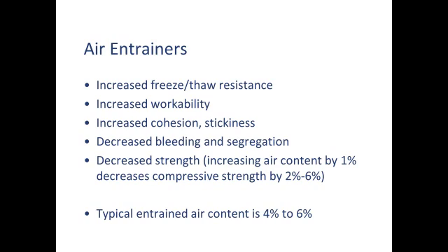The benefit of doing that is, because the air bubbles are tiny and they're sort of spherical, they do act like little foamy, spongy ball bearings. Gives the concrete workability. Also gives it some stickiness, which tends to help keep the concrete more consistent. You get less bleeding, less segregation with air entrained concrete. So for those of you folks listening who do use concrete that has been air entrained, you may recognize some of these characteristics of it being sticky and having less segregation and bleeding.